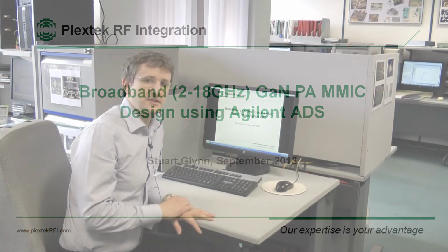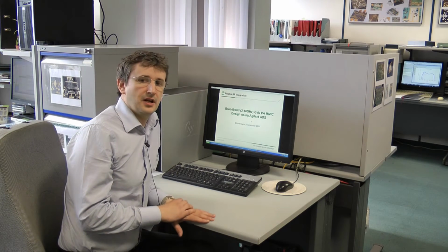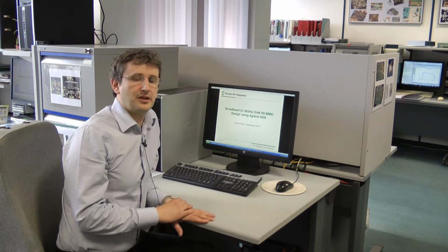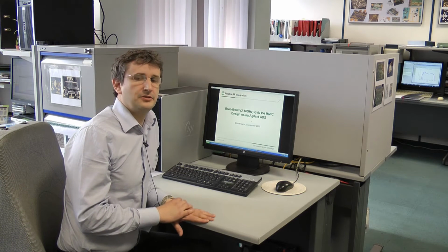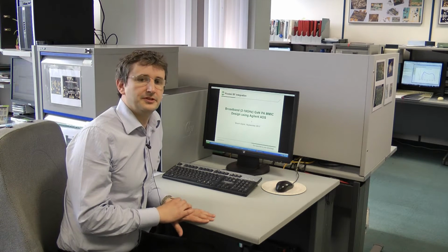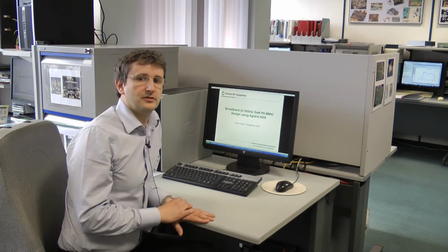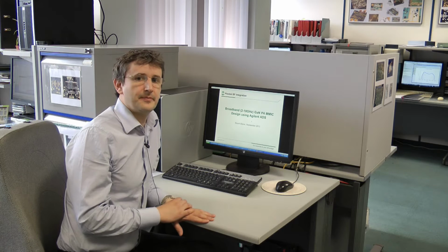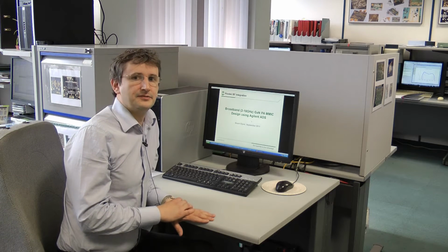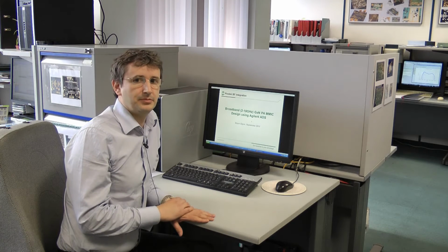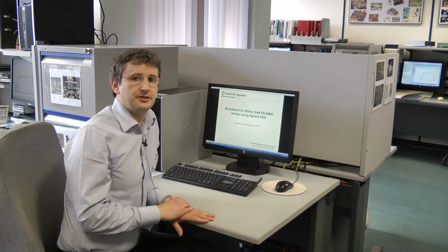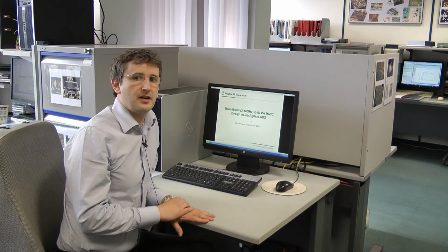Hello. Today we're going to talk about a broadband gallium nitride power amplifier MMIC design. Gallium nitride processes with transistors suitable for operation at microwave frequencies are now commercially available from a number of foundries. Gallium nitride transistors have a higher breakdown voltage and maximum junction temperature and are particularly suited to the realisation of high power amplifiers.